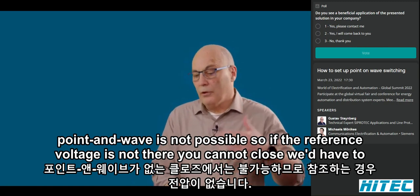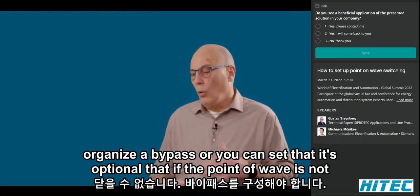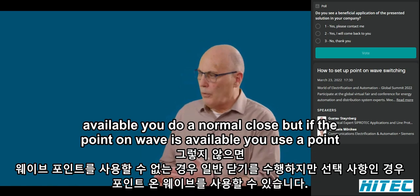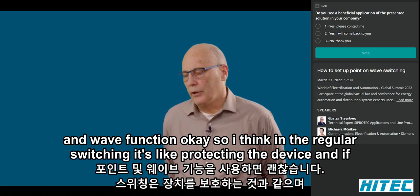So if the reference voltage is not there, you cannot close. We'd have to organize a bypass, or you can set that it's optional, that if the point-on-wave is not available, you do a normal close. But if the point-on-wave is available, you use a point-on-wave function.